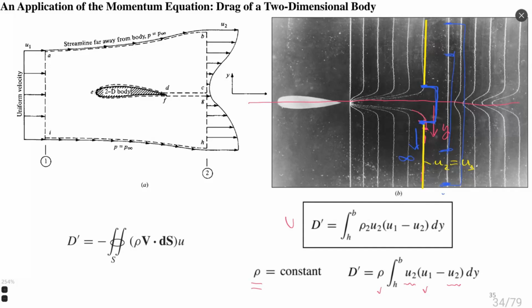And this, as you may see, has some thickness, which could be compared with the thickness of the airfoil. Approximately, looking at this picture, it is more or less 3 times, maybe 4 times the thickness of the airfoil. So we can define this limit as plus minus 2 thicknesses of our airfoil. This is where we need to calculate the integral. We do not need to calculate it at a very far distance, right?